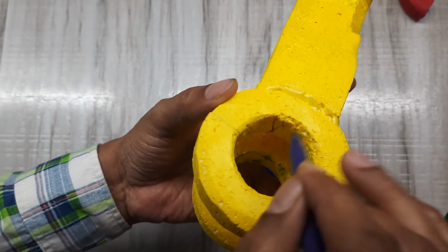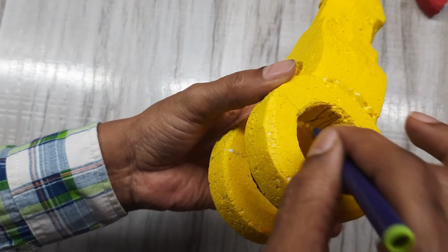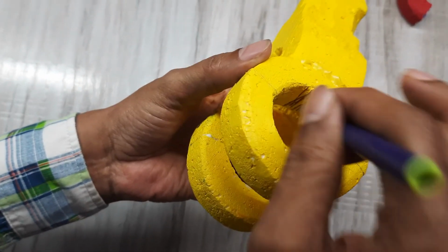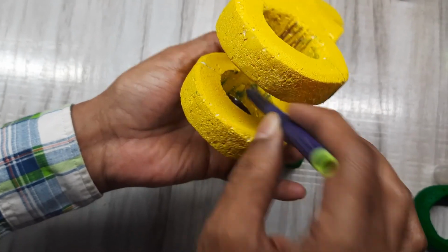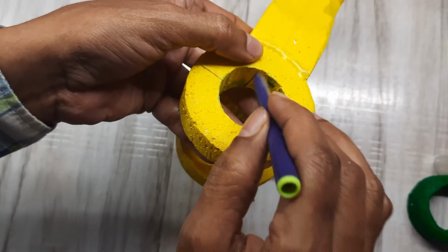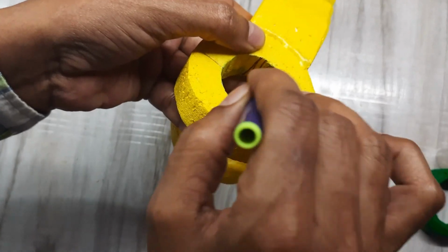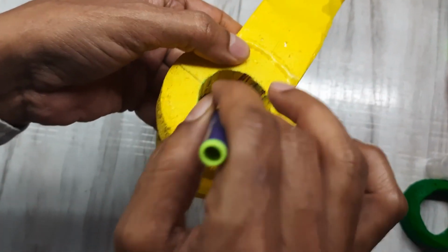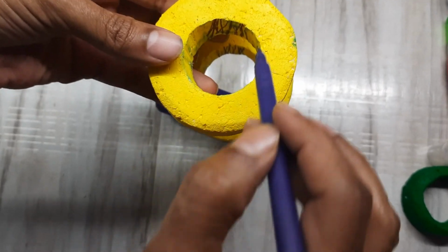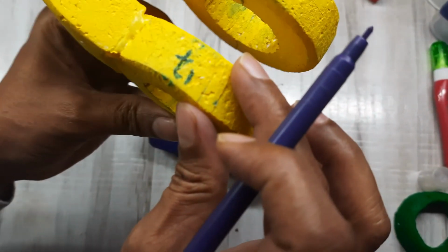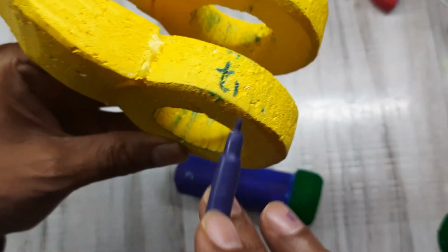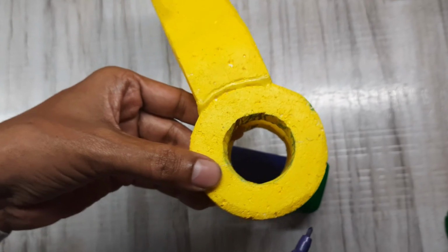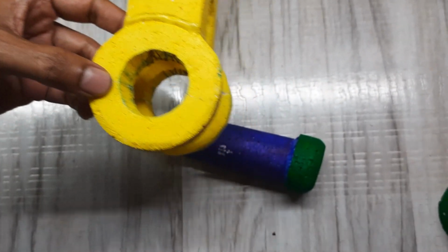So here I am showing that at this region the crushing will take place. The same way, the crushing will take place at this position also. I'll just move like this here also. This area, and that's why the diameter is again D1, but the thickness is T1, meaning 2 into D1 into T1. That will give the crushing area for the double eye.